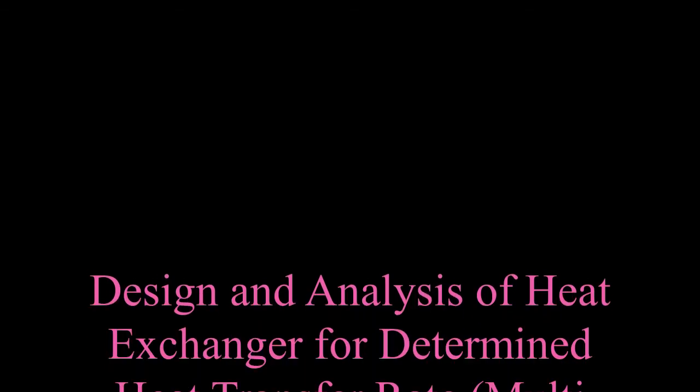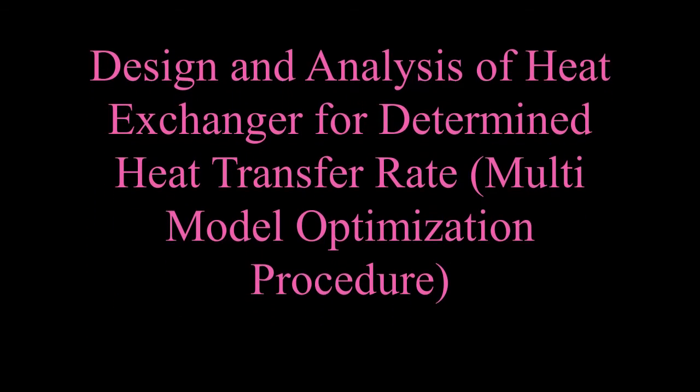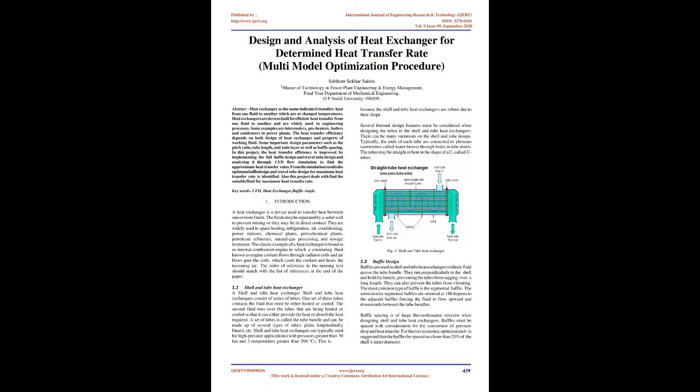Design and analysis of heat exchanger for determined heat transfer rate. Modification: implementation of full baffle into the shell and tube heat exchanger. Modeling changes: finding maximum inclination of baffle and creating various models with change in the design of travel tube. Analysis: CFD analysis on 3D model in SolidWorks.